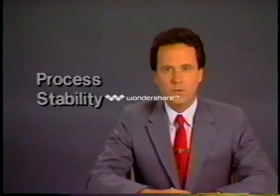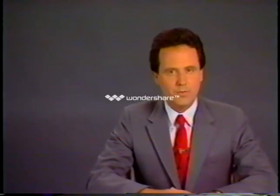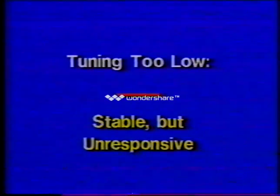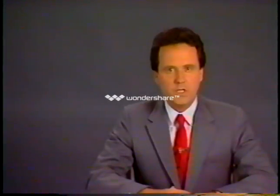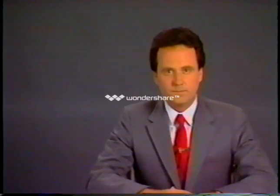As we will see, you can make a loop very stable by tuning it very low, but in so doing, you will tune out its ability to respond to change, which is why it is there in the first place. Conversely, if the loop is tuned too high, you can kiss stability goodbye since the controller will be calling for changes that are more drastic than the process can possibly accommodate. The achieving of the proper balance between stability and responsiveness is the art of good tuning.